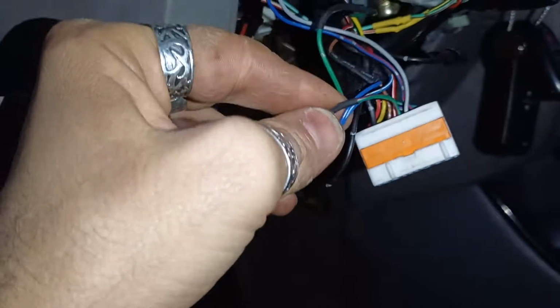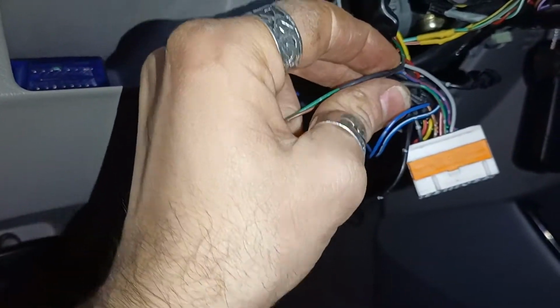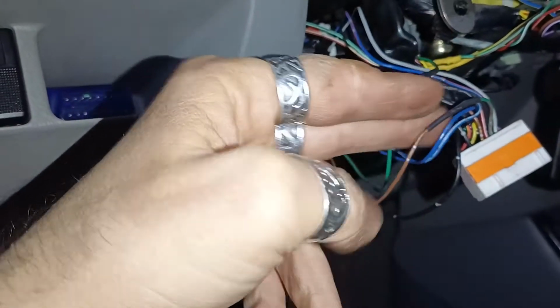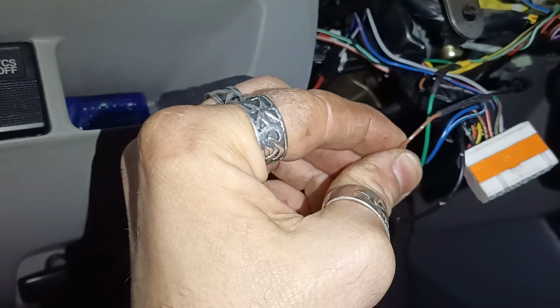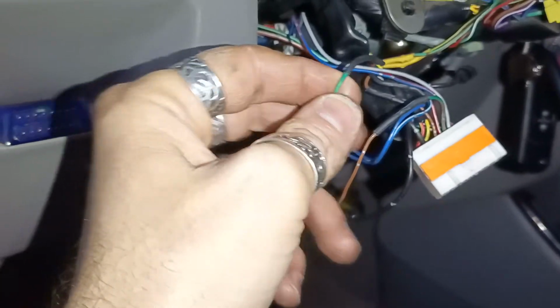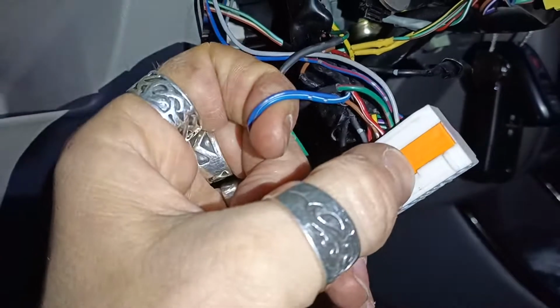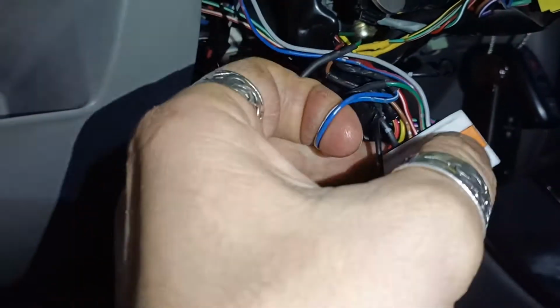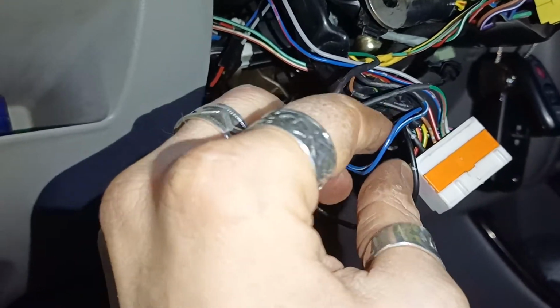Then this wire right here, if you have followed the previous episode, was one wire. You need to cut it. The one that goes into the connector is for the pin of the DRL of the auto, and the one that goes towards there is going to the coil of the DRL. So these two signals you need, and then those two, the red with white and these brown ones, are for the TNS and the low beams.